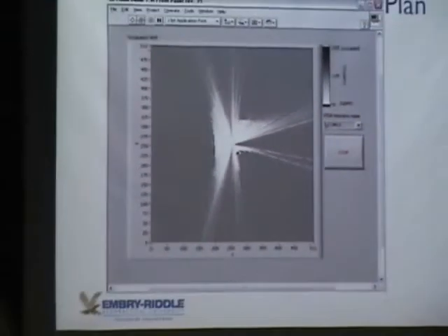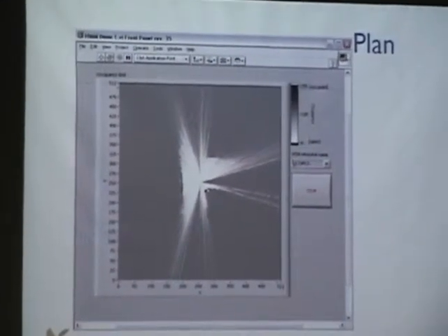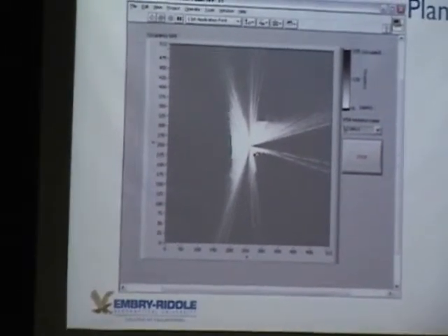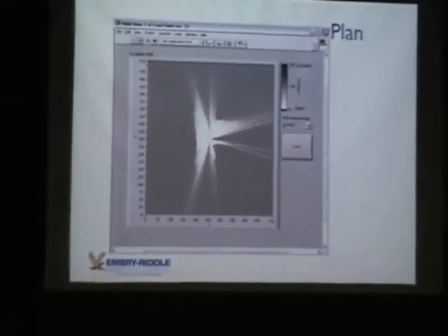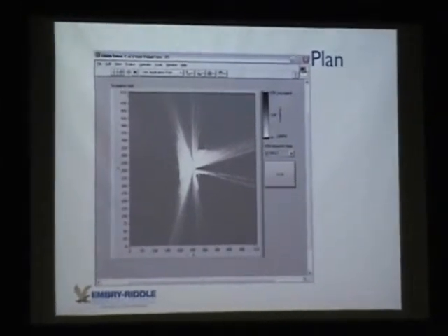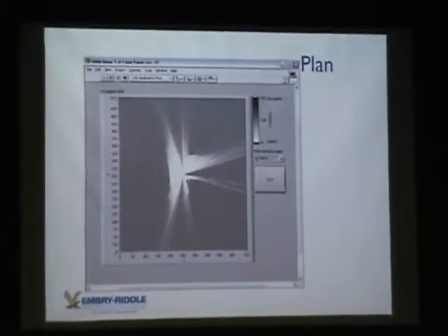The technique we're using is Sebastian Thrun's histogramic in-motion mapping, where we take the data and use that to push points up or down on a local perceptual grid. And this grid is about a 1-inch resolution.